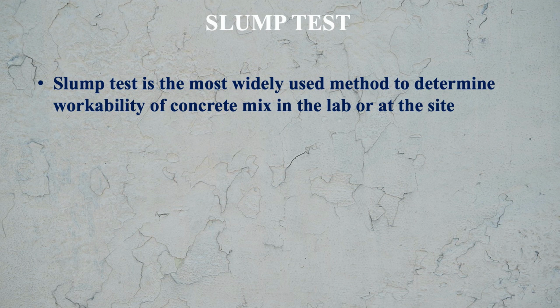Slump test is the most widely used method to determine the workability of concrete mix in the lab or at site. This is a very simple test and its equipments are also very light, so you can easily transport the equipment to the field. So that way it is very popular as a field test.